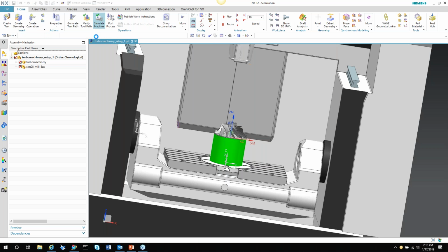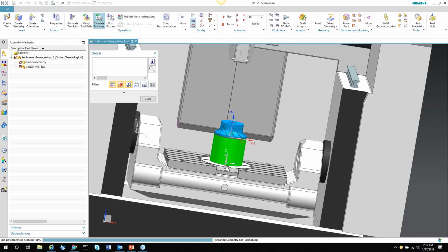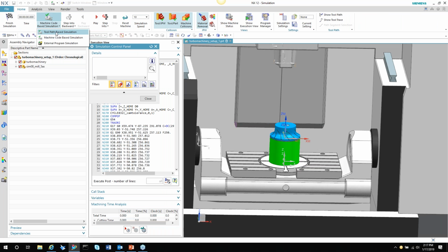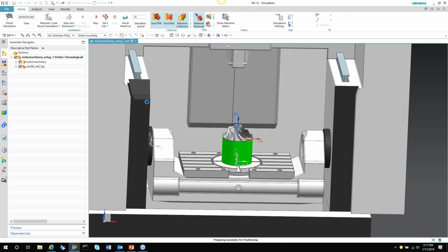is incredible. So I used to program these types of axial impeller blades out of Hastelloy and Inconel with systems like EdgeCam and Hypermill, and they were intensive. They were 30 operations strong. There were very few full 5-axis operations because of the complexity, and NX did a great job on creating an operation that has to have 4 or 5 parameters set, and to give you a full 5-axis toolpath like this